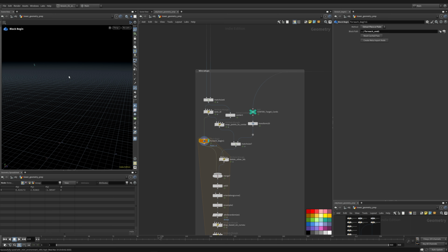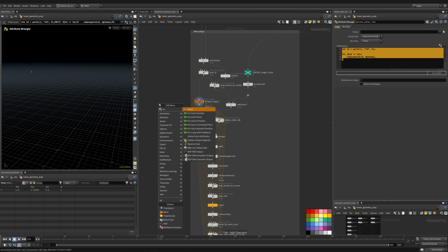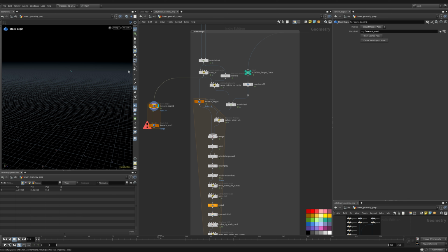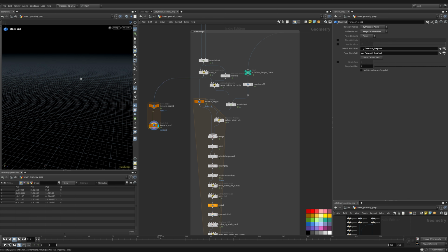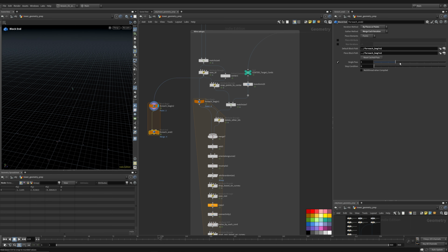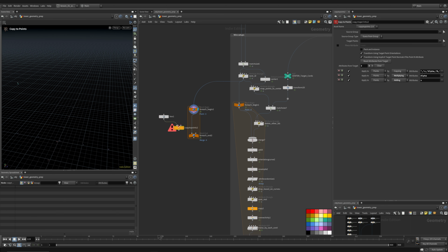And then I did a for each loop where I took each point here and connected, and then I removed points that had mismatched IDs that were different. And this probably isn't the easiest way to see if this is your first time looking at a for each loop. So I'll just try a quick explanation. So a for each loop lets us do kind of what you assume. It lets us go through each point. And if I click on this bottom one in a single pass, I can go through each point and I can do a little operation on each point.